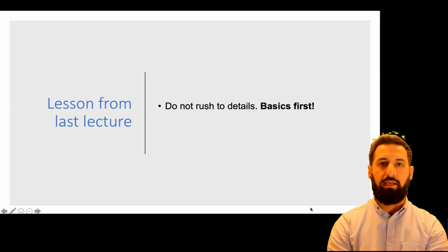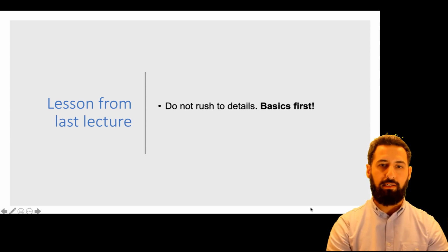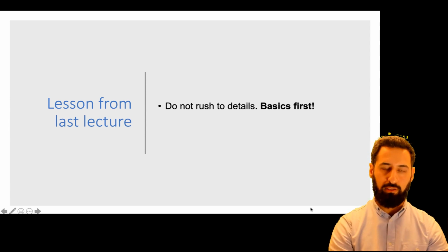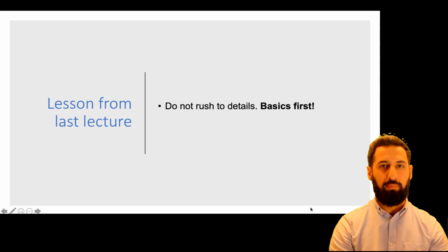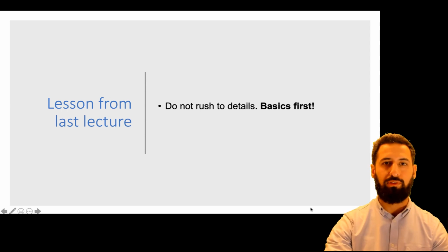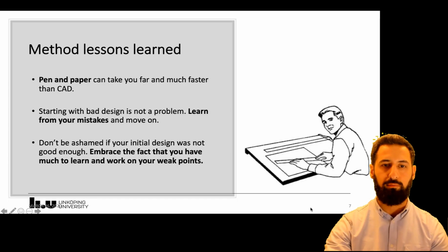Okay, another lesson from the last lecture is do not rush to details. Take basics first. Don't start doing a lot of advanced solids and surfaces. Start with the wireframes, make the skeleton work. Make sure that the model can correspond to the various requirements in terms of changes necessary. Basics first. That's the most important thing to remember.